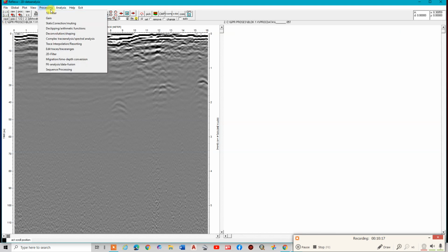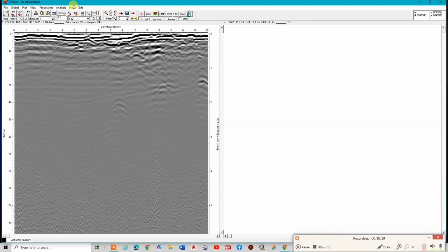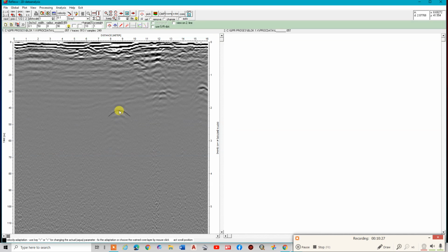And then for the last step, for me, I like to measure the velocity of the wave. Okay, this is 0.1, but I think it's a little bit slower because the hyperbola doesn't fit my mouse, except this one kind of fits. But I think it's a little bit slower, so I'll just put it here.